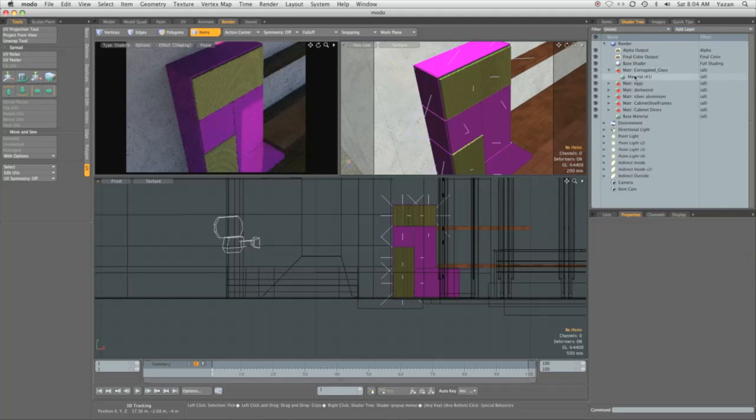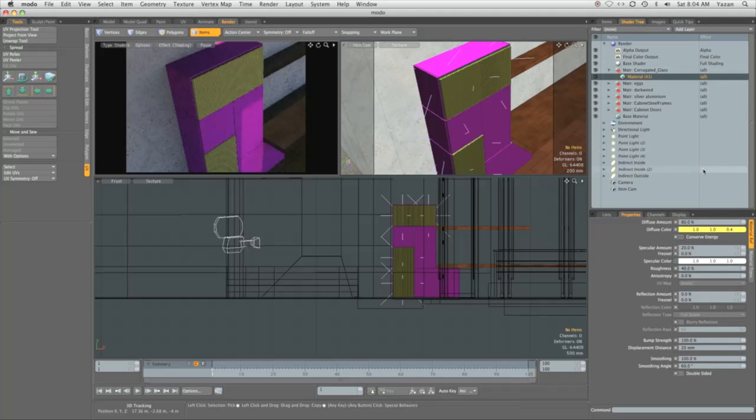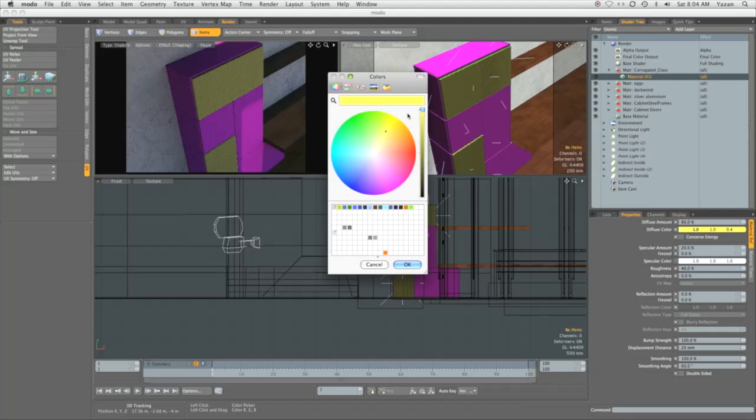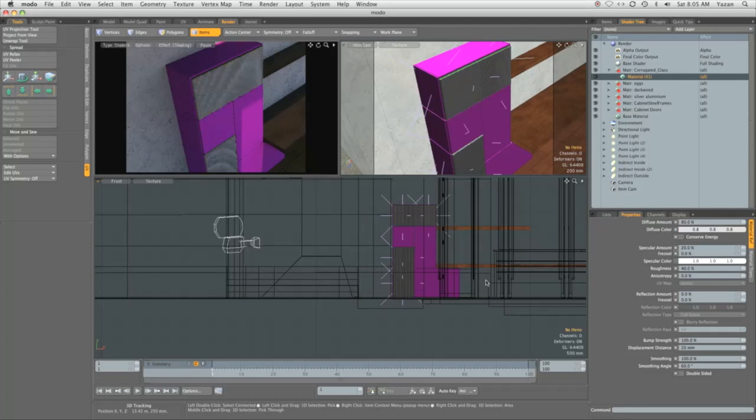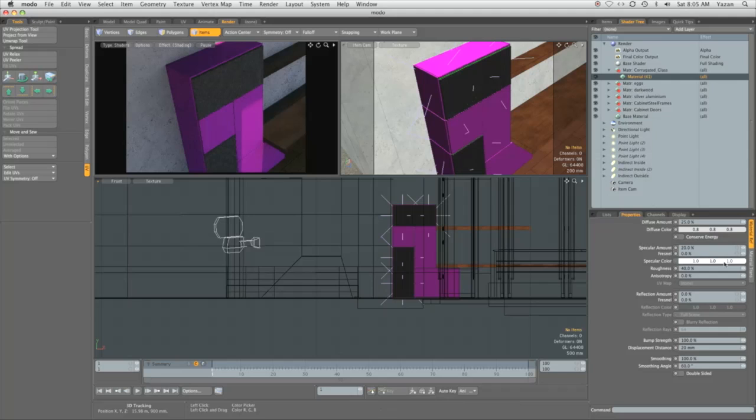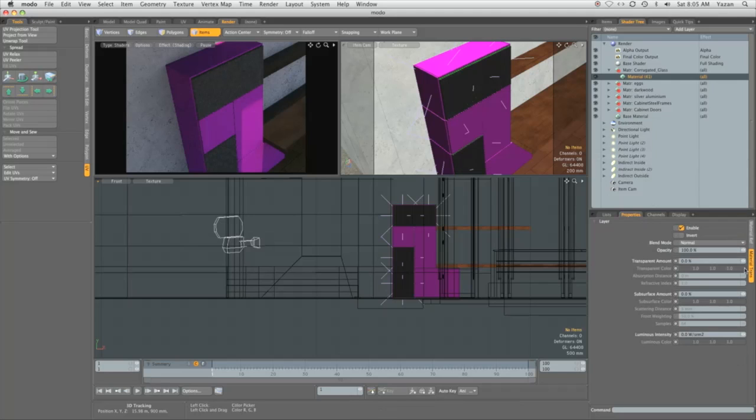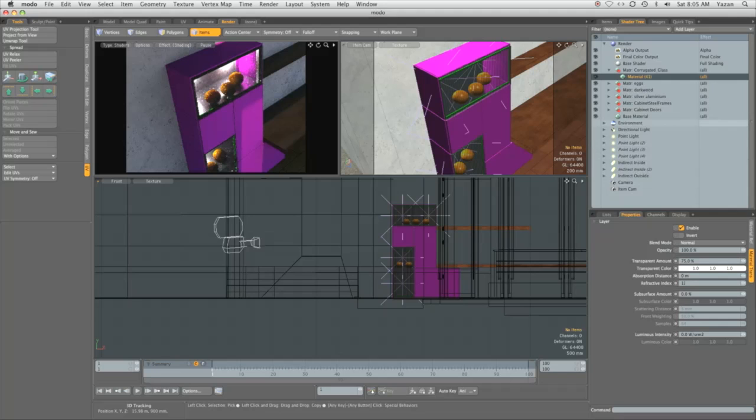Go to corrugated glass material. Let's first of all pick a nice light gray color. We've got a 0.8, 0.8, 0.8. Drag down the diffuse amount to 25%. Go to the material trans, and drag the transparency up to 75%, and the index of refraction to 1.44.